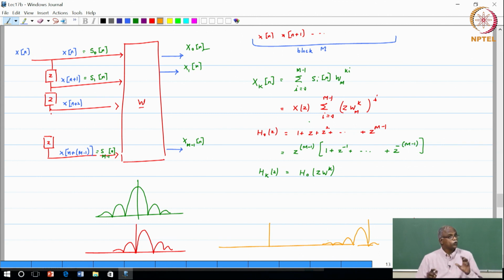Okay. So, what is DFT? It is actually taking the input signal, passing it through a bank of filters and then giving you the outputs and saying, oh, by the way, x naught, you think of it as the frequency component. Usually if somebody gives you the DFT coefficient x naught, what is your interpretation? That is the DC term. It is actually not the DC term, it is actually all the energy in your input signal that will pass through this filter that comes out as x naught.